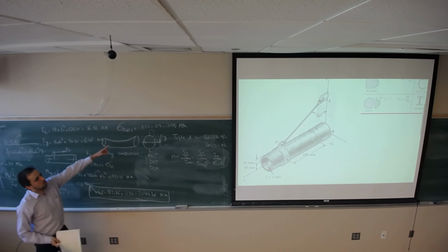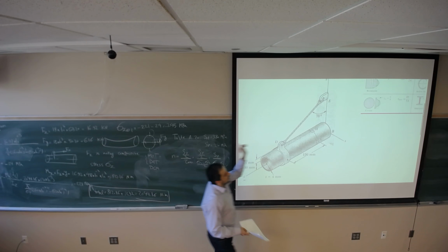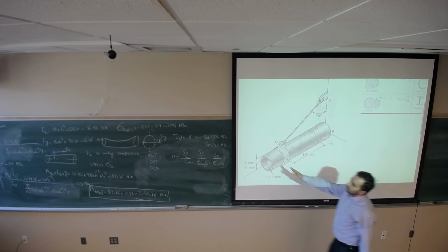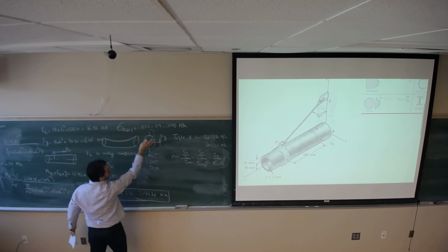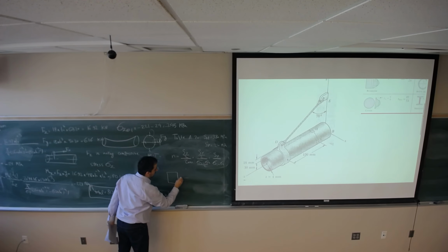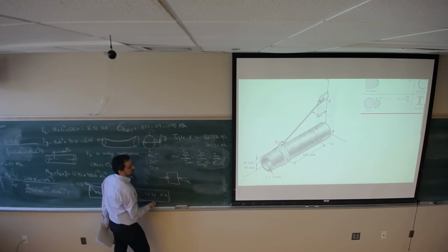The only stress that we have on point 1 is the compressive normal stress. So no shear stress, and the other two stresses would be 0.